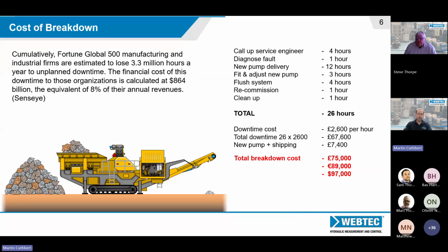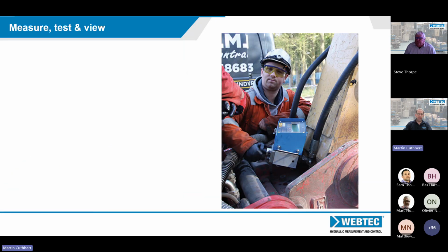What can we do, and how can we use those 4 different maintenance types to prevent that? And the tool that we want to look at then is data loggers. But where are we today? If you were to look today, for some people, your day-to-day quite often going to start with a pressure gauge. For most of us who've been in the hydraulics industry for a long time, that's what we see everywhere on hydraulic systems, a glycerine Bourdon type pressure gauge, and that will indeed tell us the pressure in the system. If we're not quite sure about the number, we might tap the front of it just to make sure that it's not sticking, but that's the kind of go-to device when people talk about pressure.